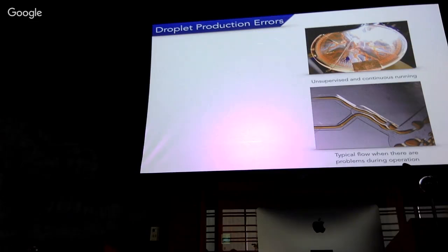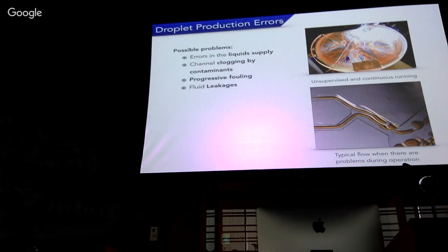Some production errors that may happen: you have your device running in stable operation, but if you have problems with the liquid supply, or clogging, aggressive fouling of your microreactors, or liquid leakages, air, or anything, then you can go from stable droplet generation to something that looks like this.